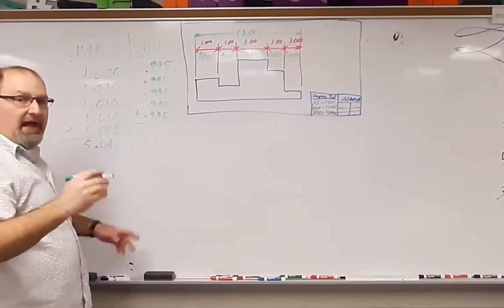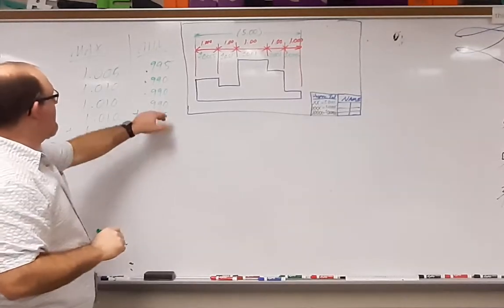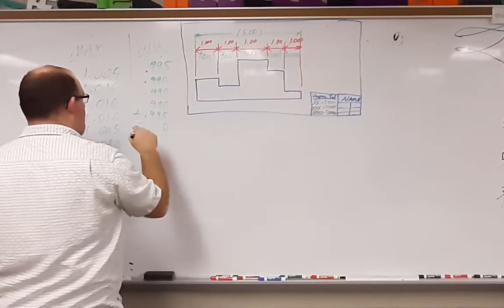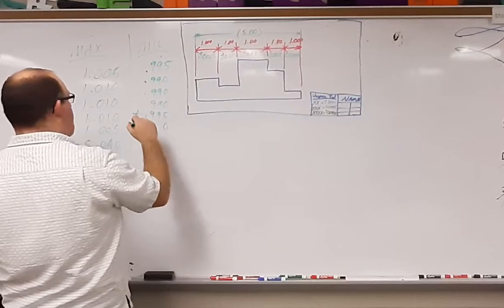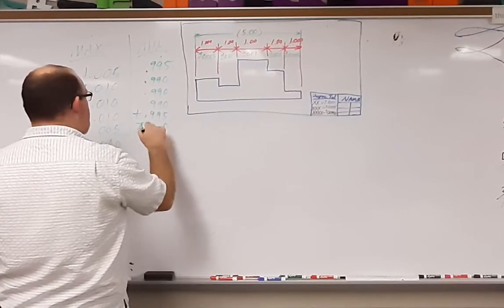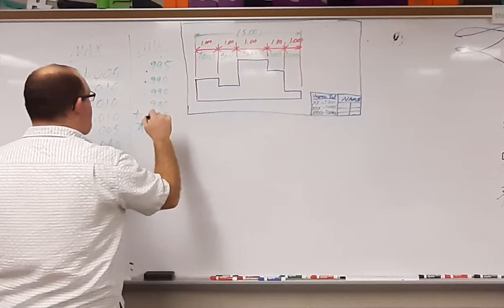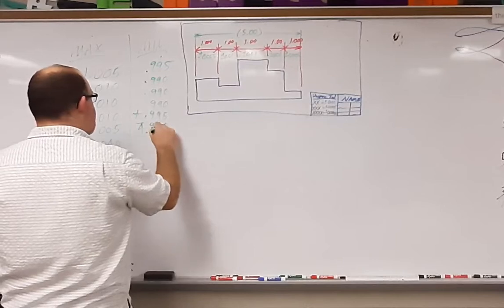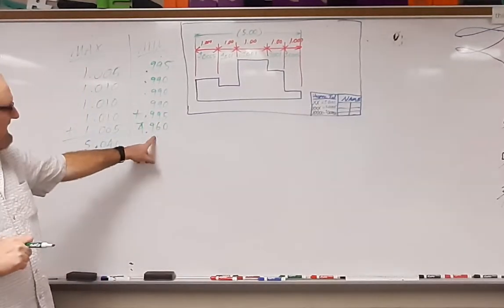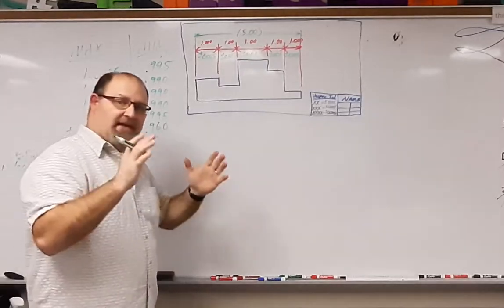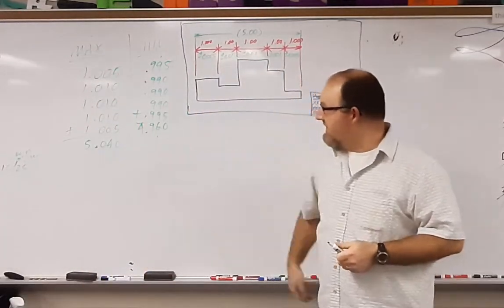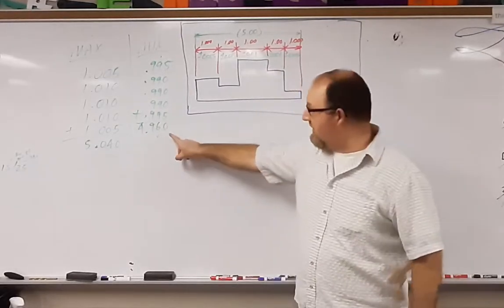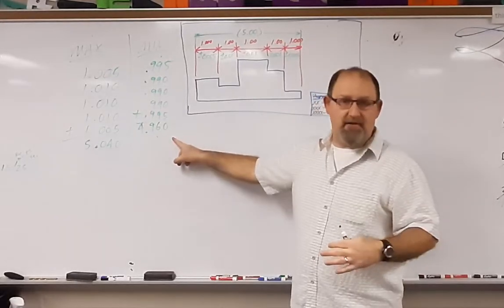And in this particular case, we'll add them up again. So 995, 0, carry the 1, 1, 2, 3, 4, 5. So 4.9, what does that come out to be? 5, 6, there we go. Okay. And so the smallest plate that can be is now 4.960. Okay? Notice this one here is 40 thousandths over the 5 inch mark. This one here is 40 thousandths under the 5 inch mark.